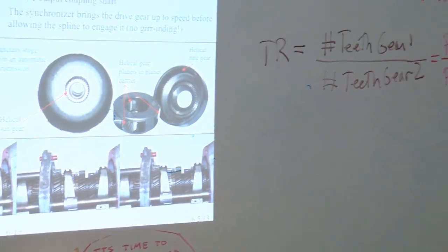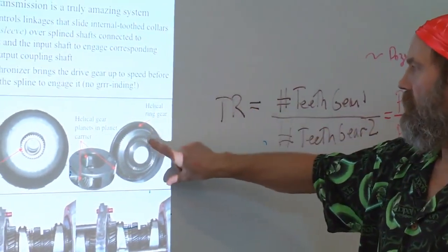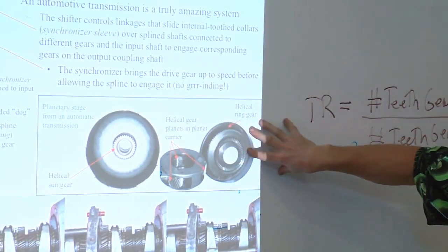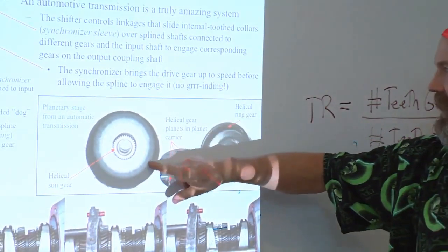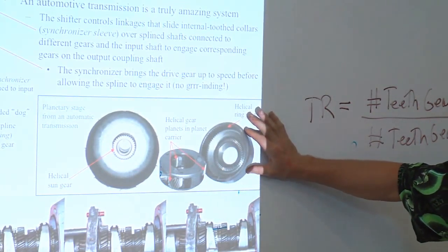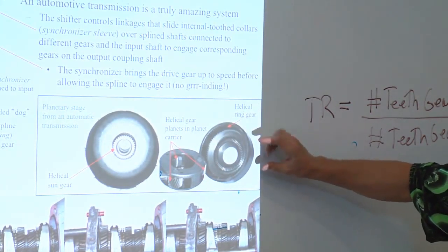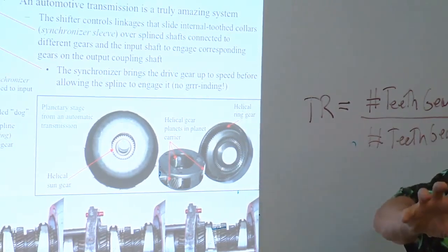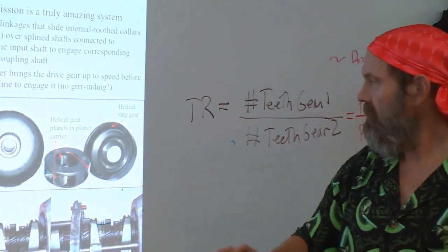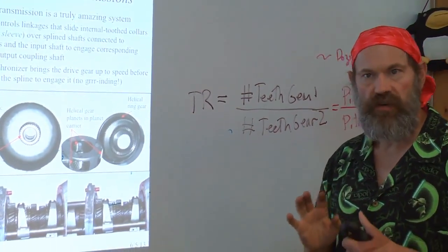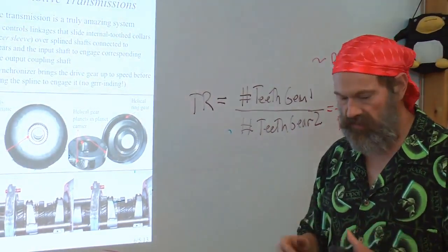In an automotive transmission, here is how planetary gears are made. The outer ring gear is actually typically formed from a piece of steel that's stamped, or a process called fine blanking, where the teeth are formed by the tool, not actually individually cut. It's amazing what you can do with very, very, very high volume manufacture.